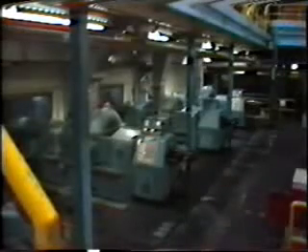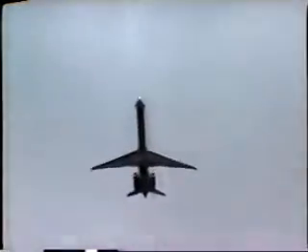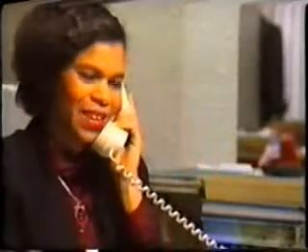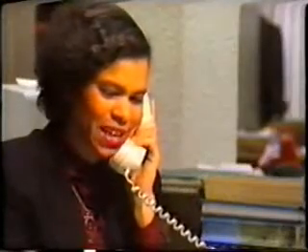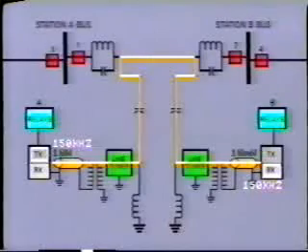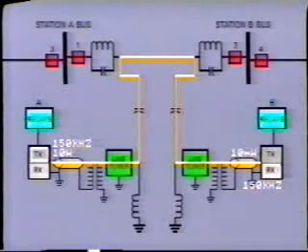Well, for one, you know that the decibel is often used as a unit of sound. You will often see reference to 85 dB on the factory shop floor or 100 dB at aircraft takeoff. It would seem logical that telephone transmission and by extension any communication transmission would also be measured in decibels, or dB for short. As used on carrier systems, the dB is actually a ratio comparing signal power into a circuit with power out, and by implication, an indication of loss.